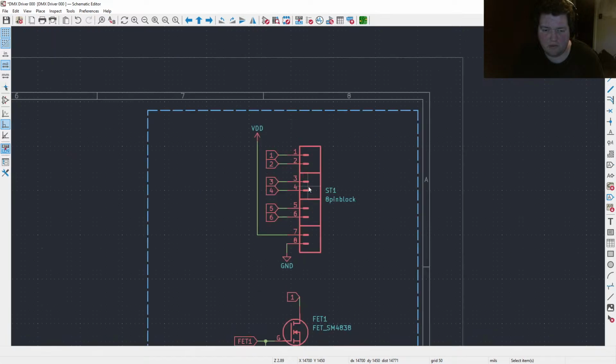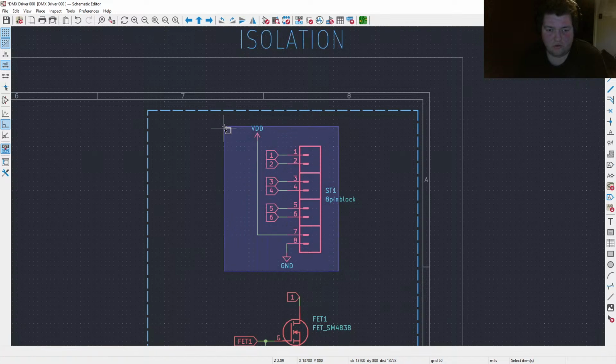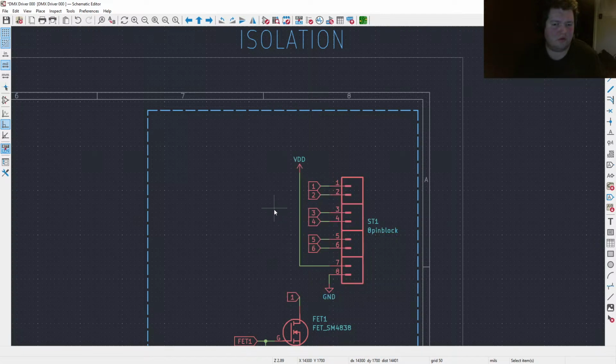The MOSFET type. In my case, the light I want to control is controllable on the ground side, so N-channel MOSFETs. I've used these particular MOSFETs before for lighting control. It's actually running the lights in my room right now. These particular ones are absolutely overkill for the light that I want to control, but if I ever want to control a different light, they'll be very handy.